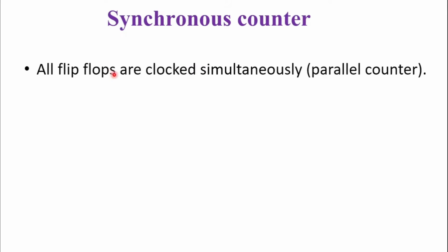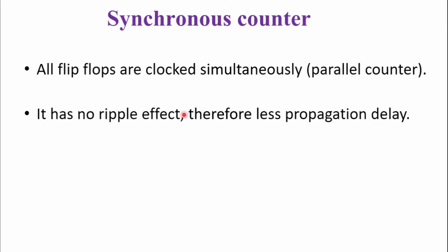All the flip-flops are clocked simultaneously, and that's why it is also called a parallel counter. Now it has no ripple effect, therefore it has less propagation delay as compared to asynchronous counter. And as it has less propagation delay, it is comparatively faster than the asynchronous counter.